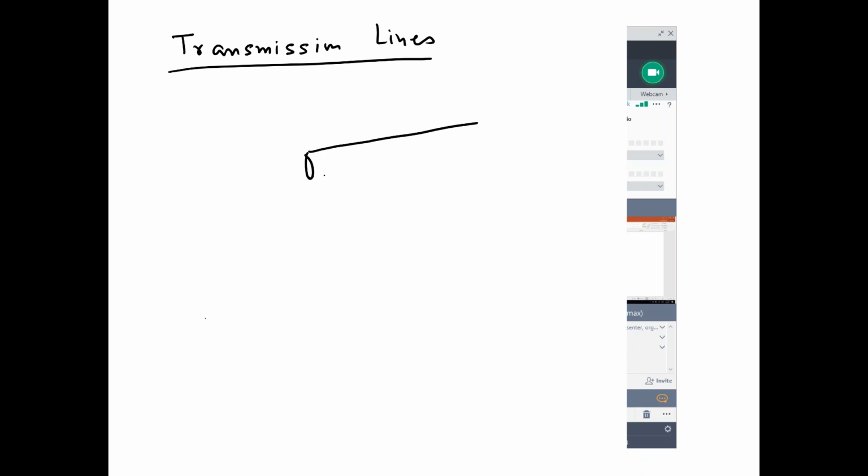Basically, if I have a conductor surrounded by another conductor, this is one very classical transmission line, which I'm sure all of you have already worked with, a coaxial cable or an SMA cable for RF regions. You have a conductor inside and you have a conductor outside. The conductor inside is trying to carry the current in one direction, outside is carrying the current in the opposite direction.